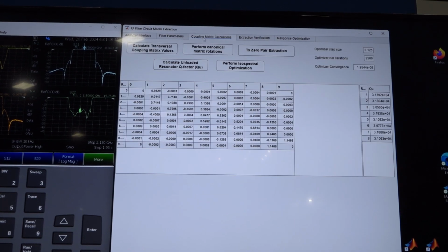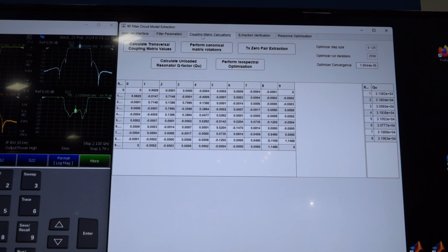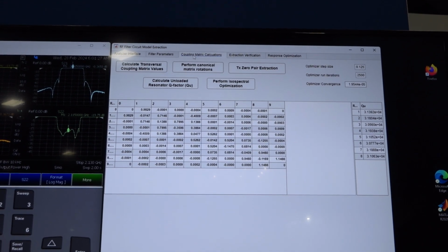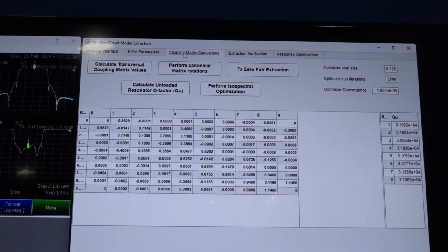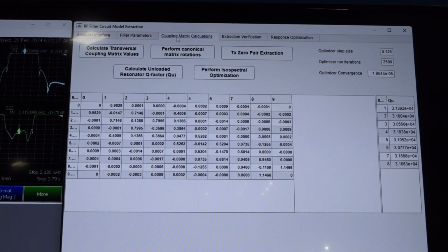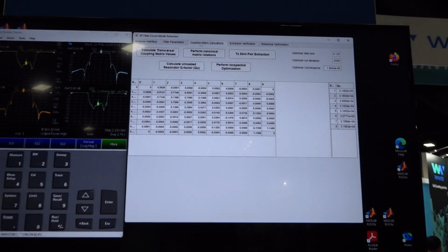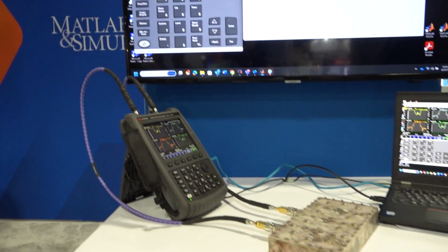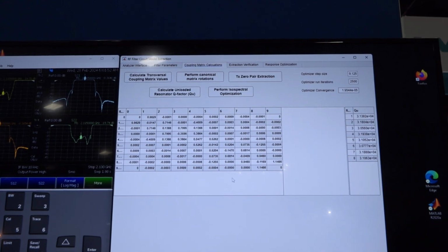One of the things in the development of coupled cavity resonant structures is what's called the coupling matrix, and the coupling matrix serves as the golden reference, or the one truth, in the cavity filter development workflow. This ties together the software development process and the actual physical prototyping. So from the previous model that was extracted, a coupling matrix can be extracted, and there are multiple representations of the coupling matrix that can be provided here.